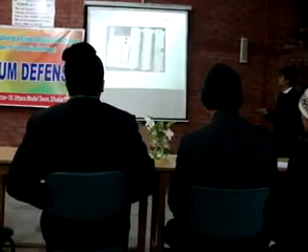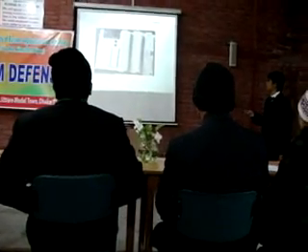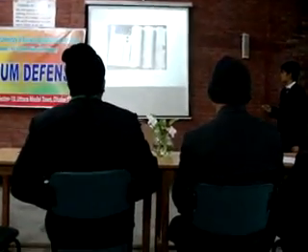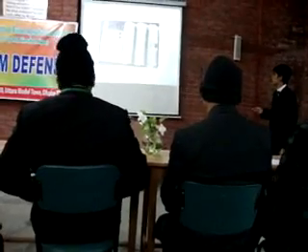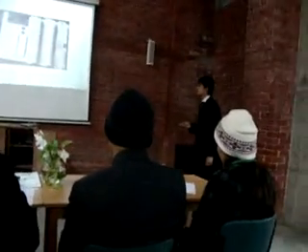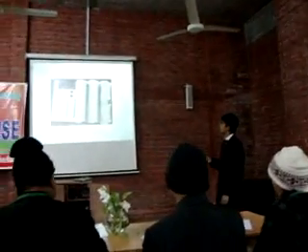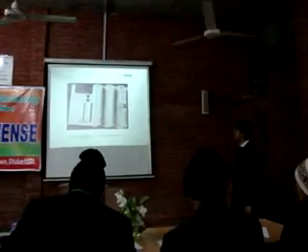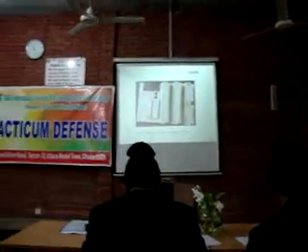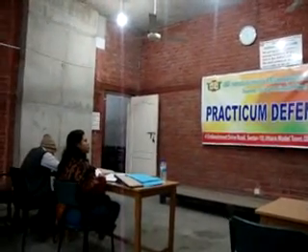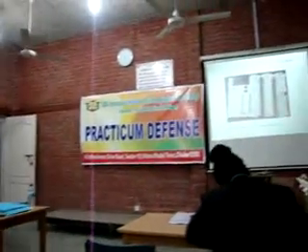And here the input power supply is given. This PLC takes 24-volt DC to operate its internal circuits. The model name of the PLC is TSX Micro 3722 PLC. This PLC is used in Niagara Textile, and it was made by Modicon Electronics. And there is the battery. This battery provides power to the PCMCIA card to store programs. This card is generally the EPROM I mentioned.